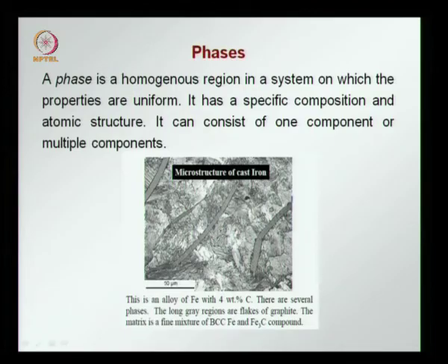Either the phase is introduced in the fabrication process, or the phases occur when solidification occurs from a melt. In concrete, for example, we have a phase which is the stone or rock phase, called the aggregates. These aggregates are mixed into a system which has cement paste, and the aggregates stay without changing their composition through the life of the concrete.